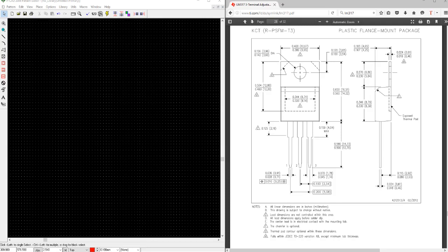Today we are going to be looking at pattern creation, and for that we are going to use the PCAD 2006 pattern editor. We are going to create the TO220 footprint, which we are going to then afterwards link on the LM317 regulator that I've created as part of the symbol editor exercise. Just a brief bit of information on the pattern editor.